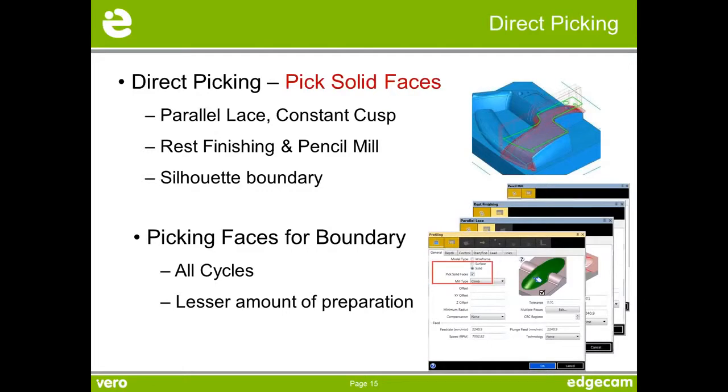And this is probably the most important, the most interesting one, I feel. Certainly in terms of saving time, this produces great benefits to us. This is all about lessening the amount of work you have to do in respect to preparing a file for manufacture. So before you create a CAM instruction, whether it be profiling, whether it be flatland, etc., I have to do boundaries, I might have to do face features, etc., etc. Well, this is now taken away. That preparation now is becoming more and more minimal as we move through versions in Edgecam.